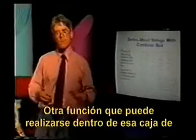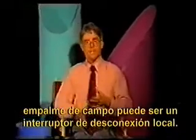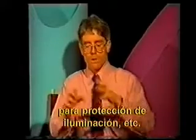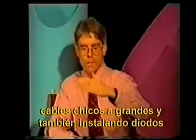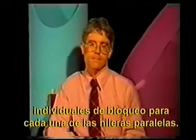Another function that might be performed within that field junction box might be a local disconnect switch. We might also install some lightning protection equipment and so on. So that would be the location where we could conveniently combine many functions, going from small wires to large wires, and also installing individual blocking diodes for each one of our parallel strings.